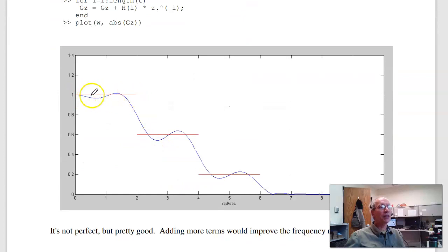Plotting it, I should have the stair step, and it's not too bad. It's a little bit off, but it's off because I truncated between -5 and +5 seconds. I only used 100 data points, and it's still a pretty good approximation of it. Adding more points would make it better. Adding a higher sampling would make it better, but also harder to implement. So that is filters in the z-plane, homework set number 12.